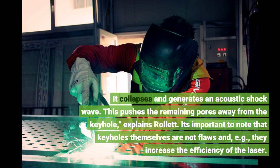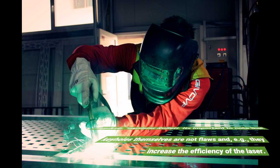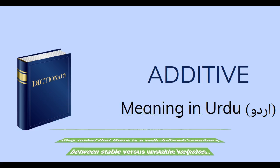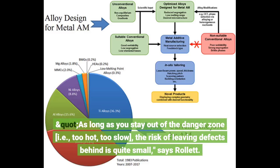It's important to note that keyholes themselves are not flaws and, e.g., they increase the efficiency of the laser. Using synchrotron X-ray equipment at Argonne National Laboratories, the only facility in the United States where the researchers could run these experiments, they noted that there is a well-defined boundary between stable versus unstable keyholes. As long as you stay out of the danger zone, i.e., too hot, too slow, the risk of leaving defects behind is quite small, says Rollett.